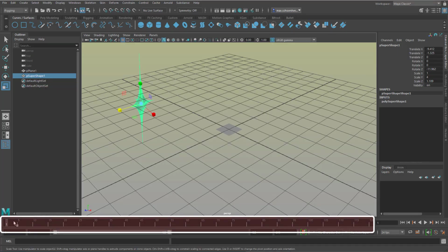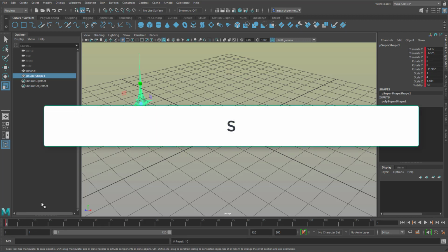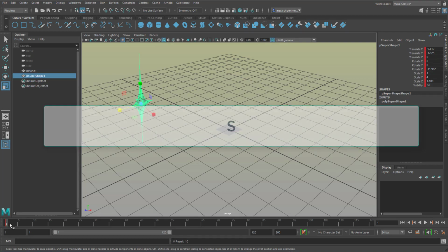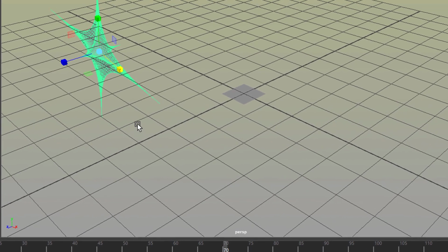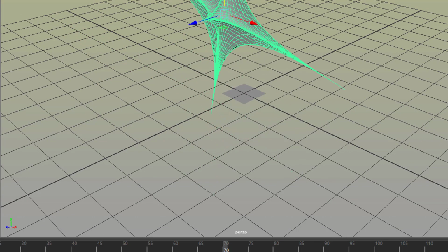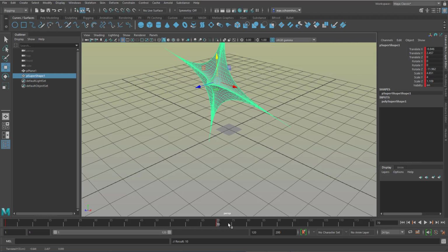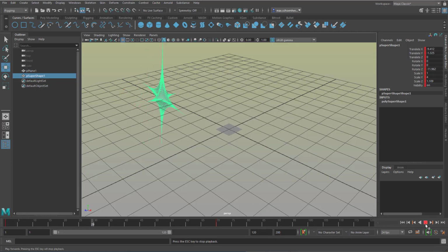And this is the animation timeline. We're currently at frame 1. When you start an animation, you start with keyframes. So with this slider here, you're at frame 1 and you press S. That makes this red. And now you go to frame, say, 70 and you make it bigger, and that's the key W now, and you move it over here and up here, and you set another keyframe by pressing S. You have a second red stroke here, and now you can go to the beginning, and now you see the animation